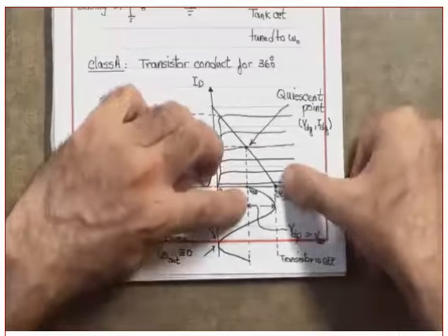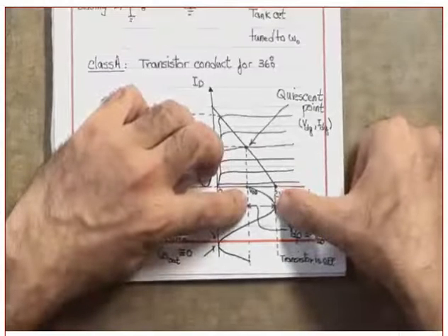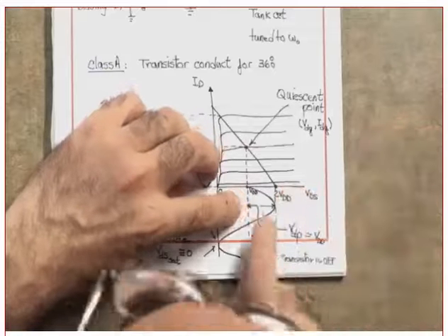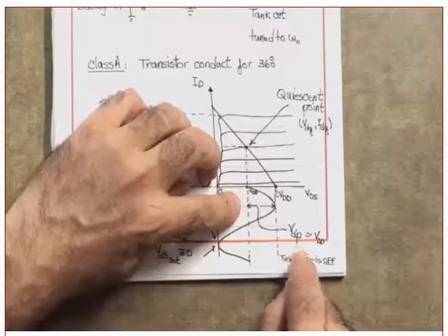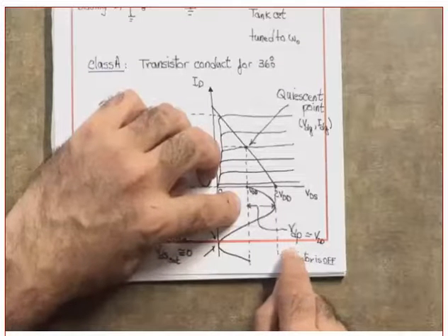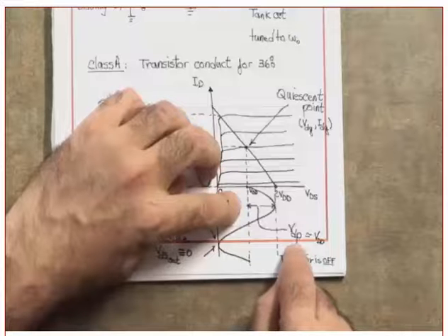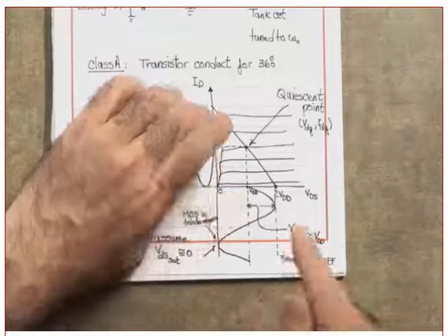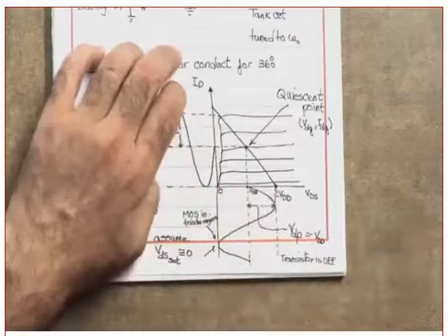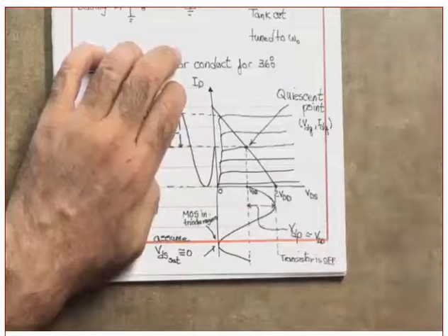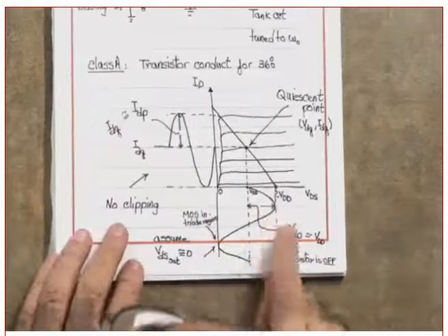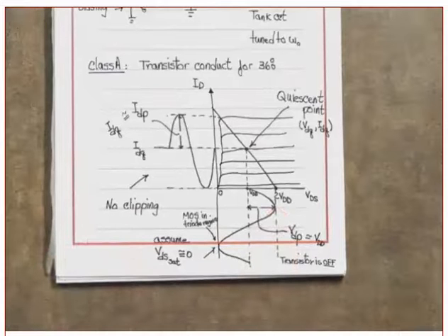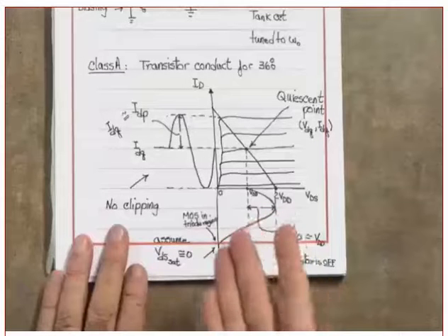Okay, now answer me the following question. Where is it going to? It is going all the way to VDD. Which means, what is this one from here to here? We call it VDP. What is the P? The P is the peak. Yes or no? Cannot hear you. That is the peak voltage. Is it the same as the fundamental in this case? You do understand we have fundamental and we do have harmonics. In this example, is VDP the same as the fundamental? Yes, it is. Why? Because this is a pure sinusoid.